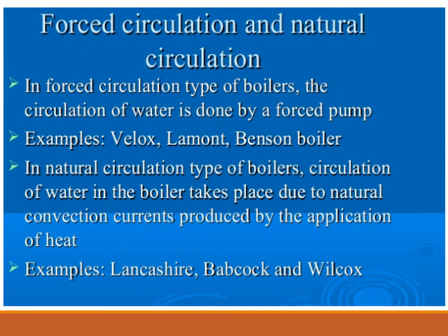Forced circulation boiler and natural circulation boiler. In forced circulation boiler, the circulation of water is achieved by means of a motor-driven centrifugal pump. Forced circulation is generally provided for high-pressure boiler. In natural circulation boiler, the circulation of water is by natural convection currents which are set up due to temperature difference.